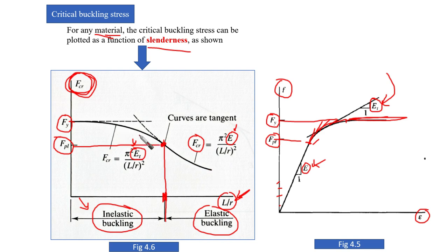However, in this part, part of the cross section is going to yield, and the remaining part is going to buckle until we reach some point where the entire cross section is going to yield and there is no buckling at all for any part of this section, which is going to be here. And this slenderness ratio means what? Exactly, it is a stocky column. So we're going to find that yielding is going to take place here.